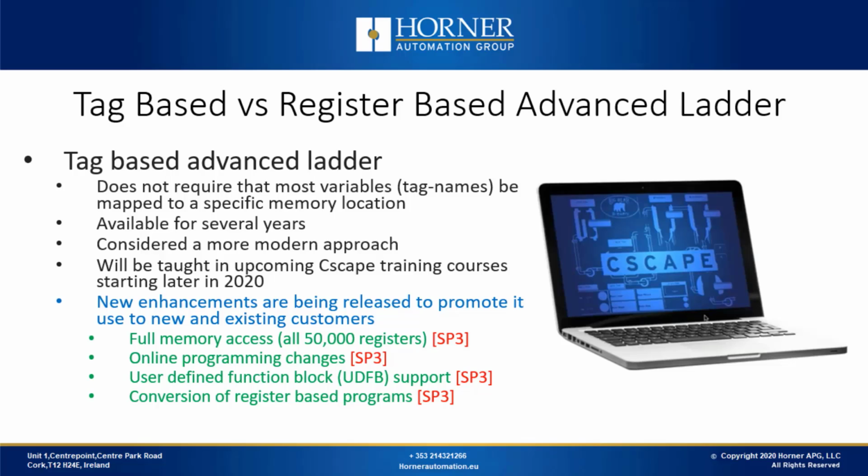You will also be able to make online programming changes, which is a method of making programming changes without stopping the controller. User-defined function blocks is a key feature that has been added in tag-based logic, which we already have a full webinar explaining. The last enhancement is one that will be very important for those of you who have lots of pre-existing register-based libraries, as we are introducing the ability to convert your register-based projects over to new tag-based versions. This enhancement will come with Service Pack 4, which will be coming in the near future.